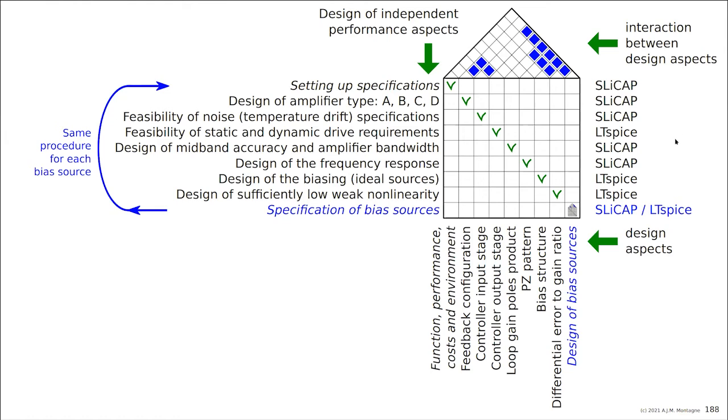Then we need to go to another simulator, a numeric simulator that needs biasing. Otherwise we don't need it, and that saves a lot of time. As you have seen, we can do the whole design of the amplifier with the signal path without really calculating the bias points. Now, we need the relation between geometry, bias point, and small signal parameters, and those relations are captured in SLiCAP.